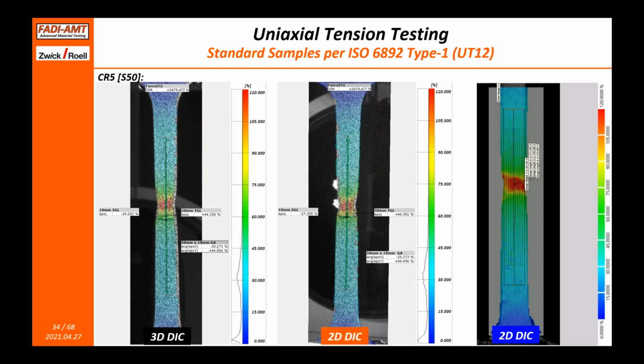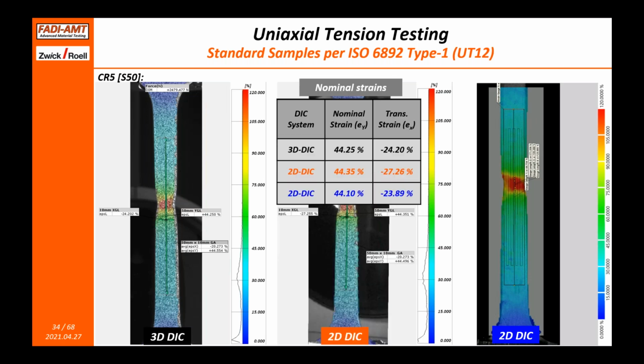This is the steel. This is a very ductile steel with 45% elongation typically. And we did the same exact experiment, we noticed the same thing. When I compare the results, the major strains are almost exactly the same. This is the total ductility of the material, and I'm seeing no difference, or a difference of no more than 0.15% from a 45% material.